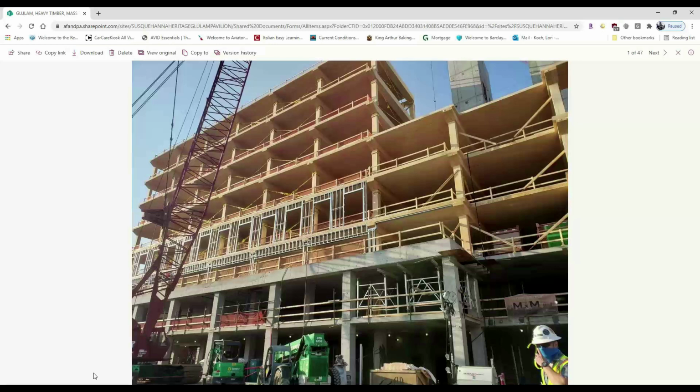Yeah, for sure. So we're in the Pacific Northwest. It rains a lot up here, and this is something that we've spent a lot of time on as far as coming up with good moisture management plans while on site. As Lori mentioned, CLT really is intended to be an interior use product as of now. And so it is important to have that moisture management plan. Sometimes it can be something simple, if a rain event occurs, having a laborer available to push water off the top of the CLT panels.